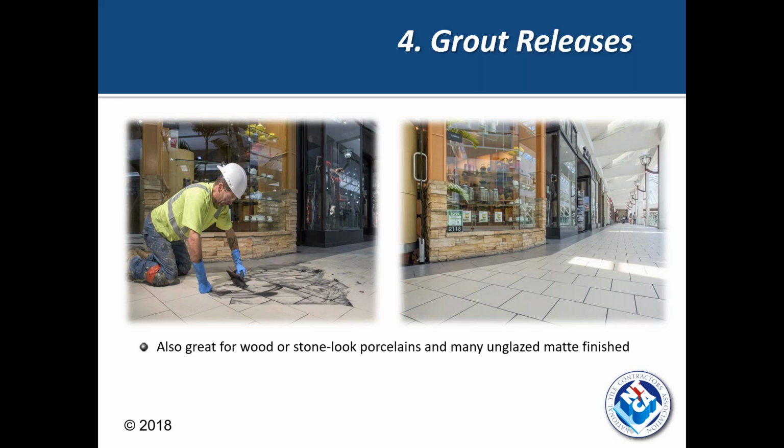but in the case of grout release, these are typically film forming detergents or soaps or various materials that you roll on or sponge on, different ways that it can be done. Let it dry, typically 15, 20, 30 minutes, and then you're grouting.